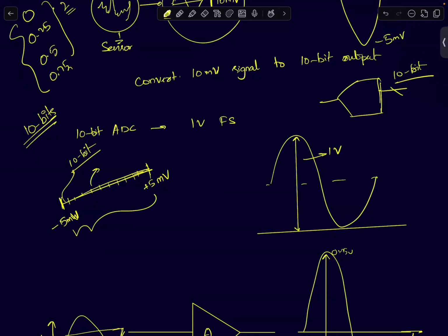That's what I'm doing. But I'm giving you additional information. The guy has access to an ADC. This ADC can be present in a microprocessor or a microcontroller chip. It can be inside a microcontroller chip also. It turns out that the ADC is a 10-bit ADC. Okay. But it needs inputs from 0 to 1. If you feed a real number between the interval 0 to 1 to this ADC, then it will convert it to an equivalent 10-bit output.